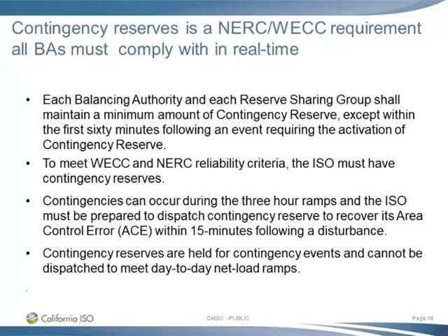So this is what goes in behind adding the contingency reserve requirement. We only add a portion of that, which is the spinning portion of the contingency reserve requirement. We get into that, I think, in the next slide. But whenever you have a contingency on the system, we've got 15 minutes to get the system back to where it was prior to that disturbance. This is why, spin, non-spin, it's a 10-minute requirement.